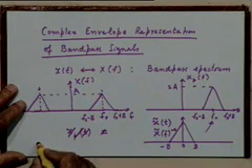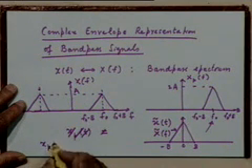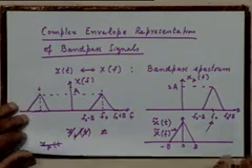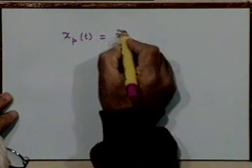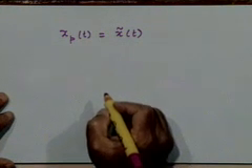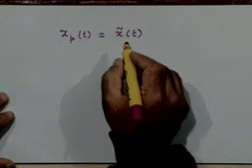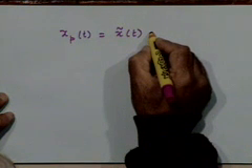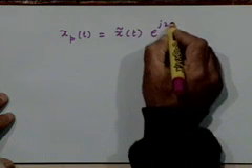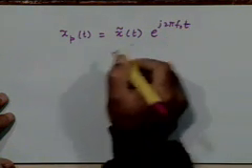So you can think of xpt as a frequency translated version of a complex valued low pass signal x tilde t, so that xpt is equal to x tilde t e to the power j2 pi f naught t.